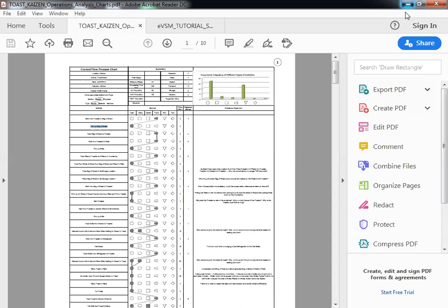And then the value stream map below it will have a flow process chart and a spaghetti diagram, because those will capture all your non-value added work. You do your best to eliminate the non-value added work, because if you did not do that, you could not do all the line balancing calculations, takt time calculations that value stream mapping will expect you to do. So I think process improvement should come before value stream mapping.